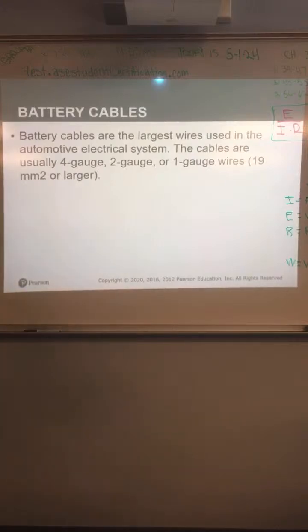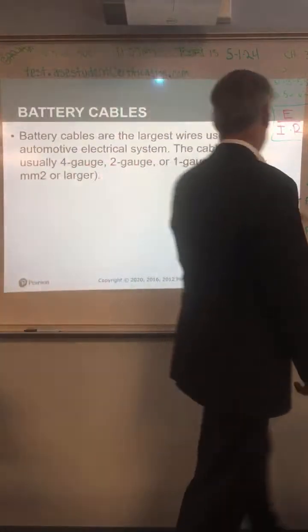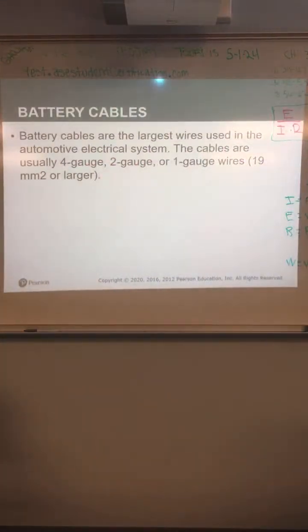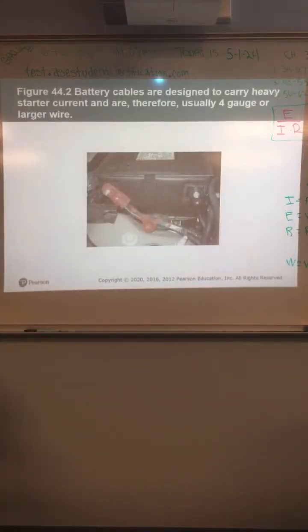Okay, the battery cable is the largest wire in the electrical system, usually around 4 gauge, sometimes 2, because they carry a lot of amperage, okay? They're designed to carry the heavy starter current. They're usually 4 gauge or larger.